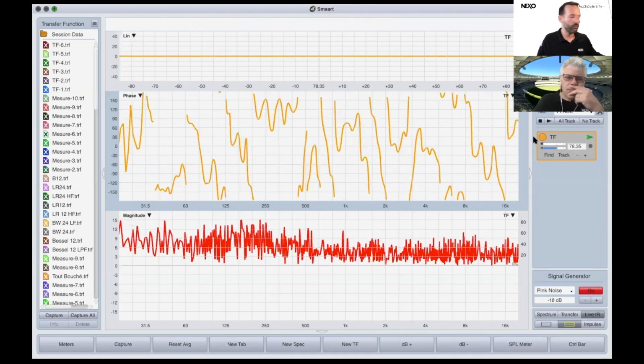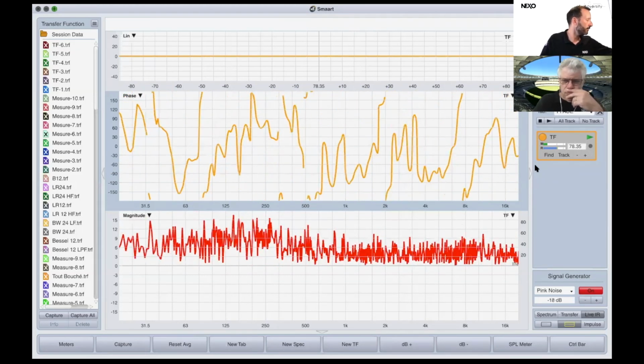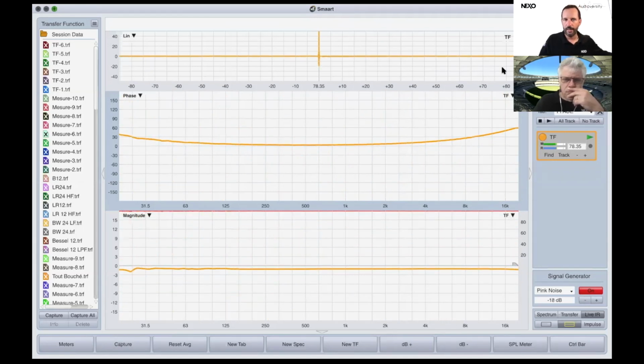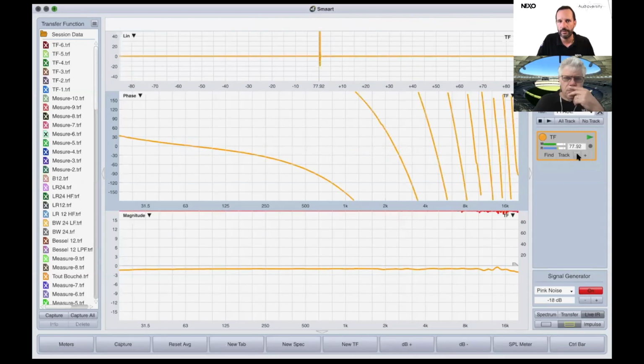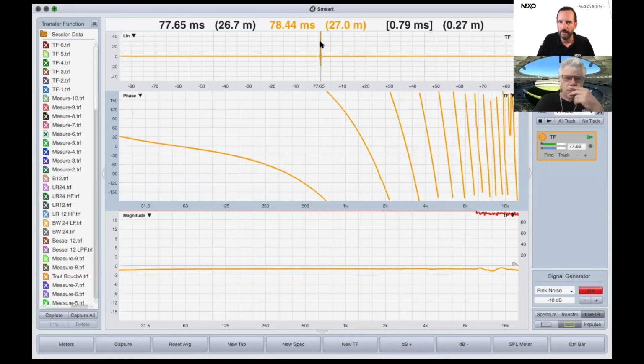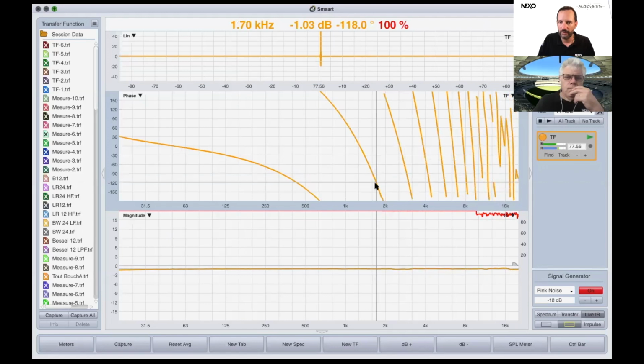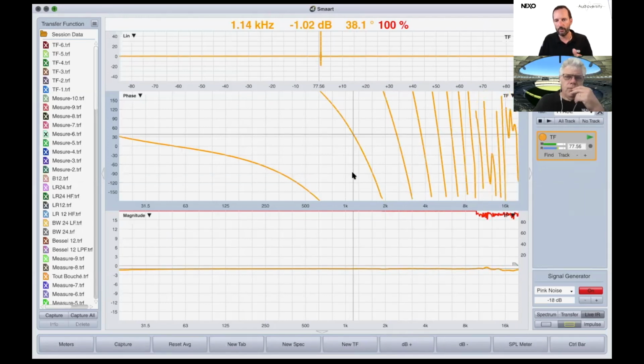As you can see here, we have our measurement system, but the delay is also affecting the phase. So what is important with this value is if, for example, my system is late. You see now that my system is late because the impulse response is not synchronized. When the system is late, you can see that the phase response is affected. And when you introduce latency in the system, you can see that the slope of the phase is going negative.